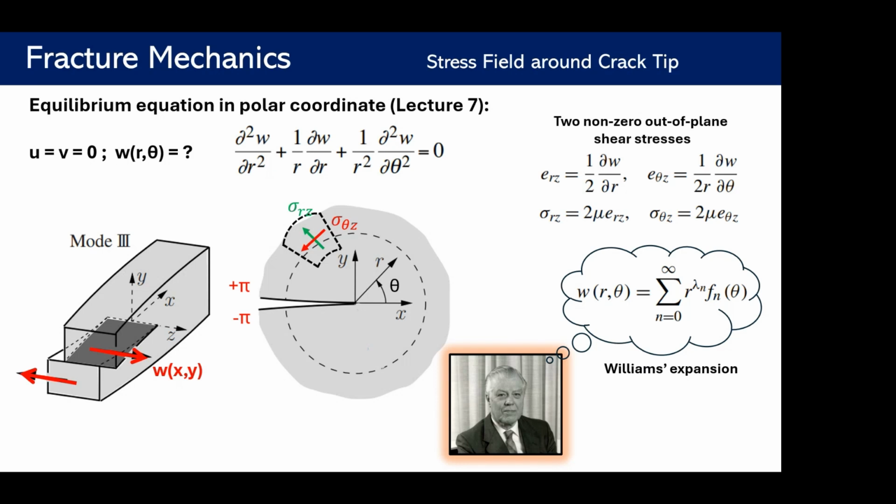And the general approach is to solve the equilibrium equations. Any problem in solid mechanics is based on solving the equilibrium equations of the system. So, for example, here is the overall approach of how we can find the stress field around the crack tip, and it's based on the third mode, the tearing mode.